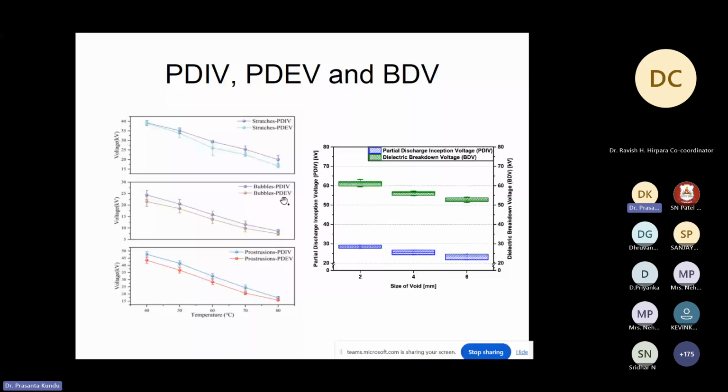So for a typical cable, you can see that the partial discharge extinction voltage is normally lower than the inception voltage, either in DC cases, AC/DC cases, or AC cases. The reason is that in this high voltage and field, because of the already present charges, discharge will continue, but discharge initiation needs something. This is a very common phenomenon which those who are in high voltage know.